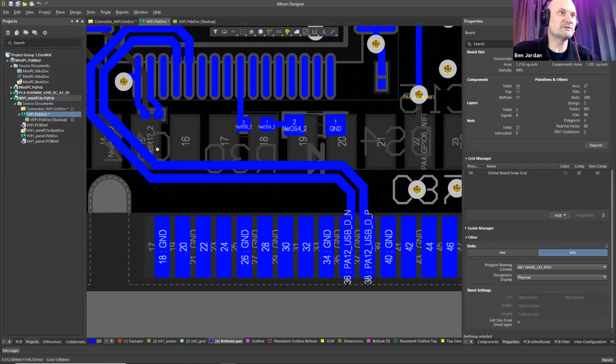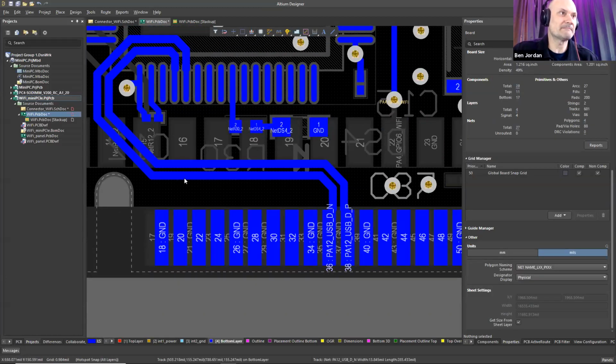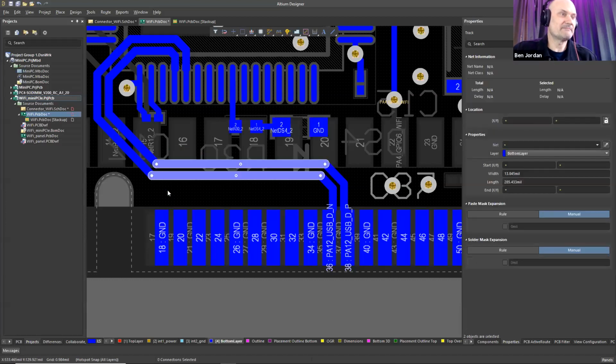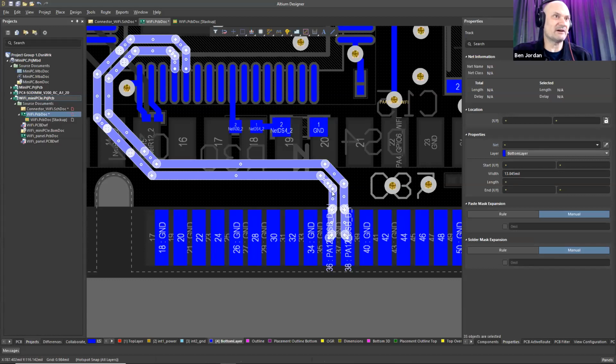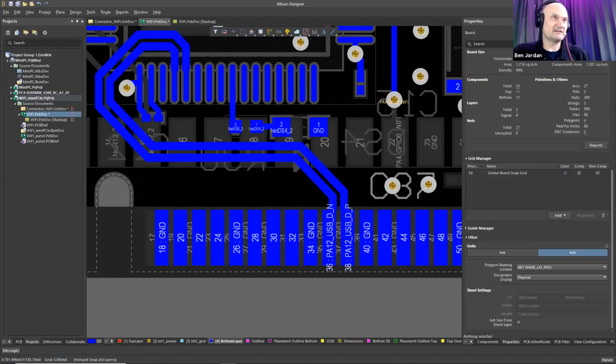And if I want to gloss this, I can select those segments, hit tab to select the whole connection, and Control-Alt-G will gloss this and improve it as much as possible. It will shorten and make the routes much more direct. And if you do that after having enabled gloss mode with curves, it'll also put curves in.